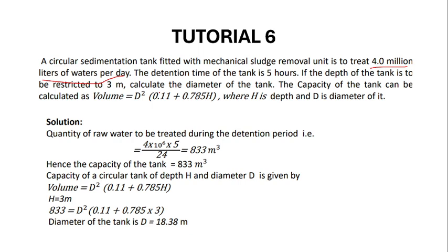And then the detention time of the tank is 5 hours, so 5 out of 24. And if the depth of the tank is to be restricted to 3 meter, H is given as 3 meter. Then calculate the diameter of the tank. D is to be calculated.